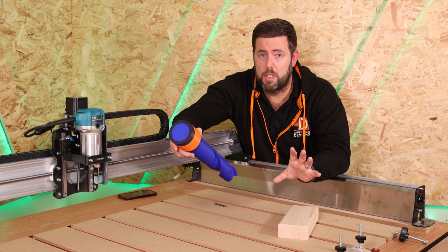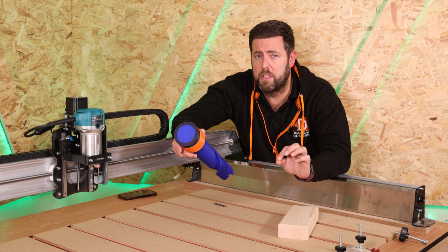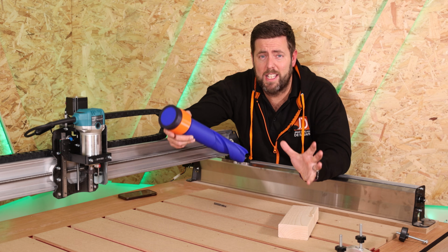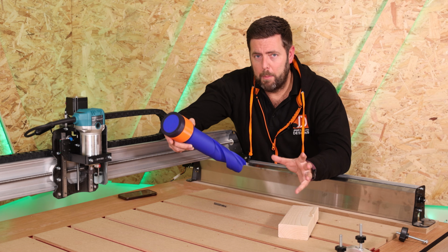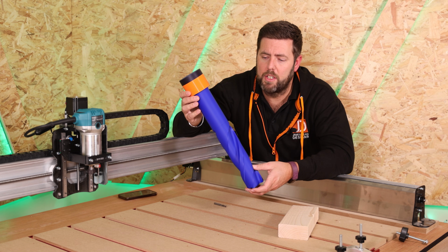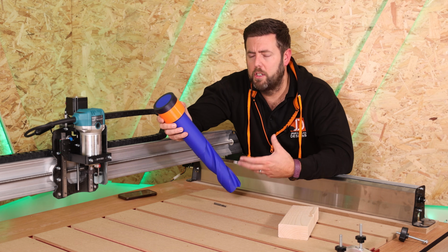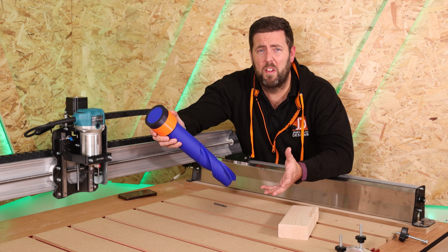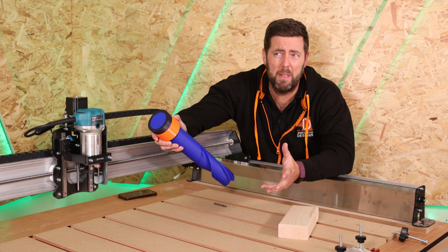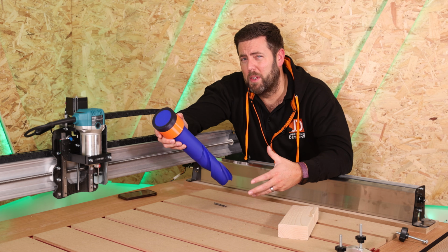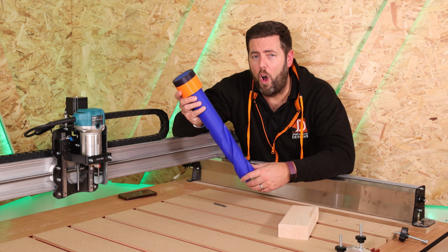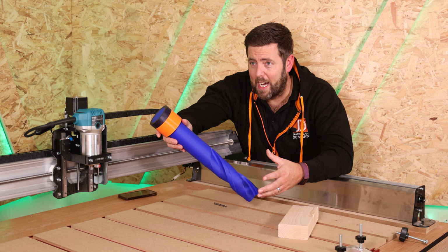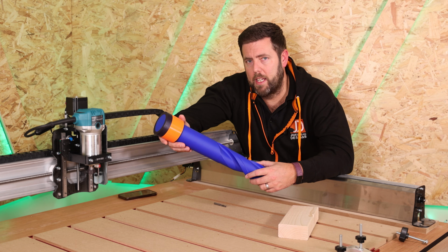Now this is no disrespect to machinists. They are very intelligent people that work to a set of defined calculations and rules that actually work. But the problem is they end up coming out with a calculation that tells you a bit like this should be able to cut up to 4,000-5,000 millimeters per minute. The problem is the machines don't travel that fast, and this is ultimately why it starts to become a problem, because the optimal speeds that this should be running at, the machine can't necessarily achieve.